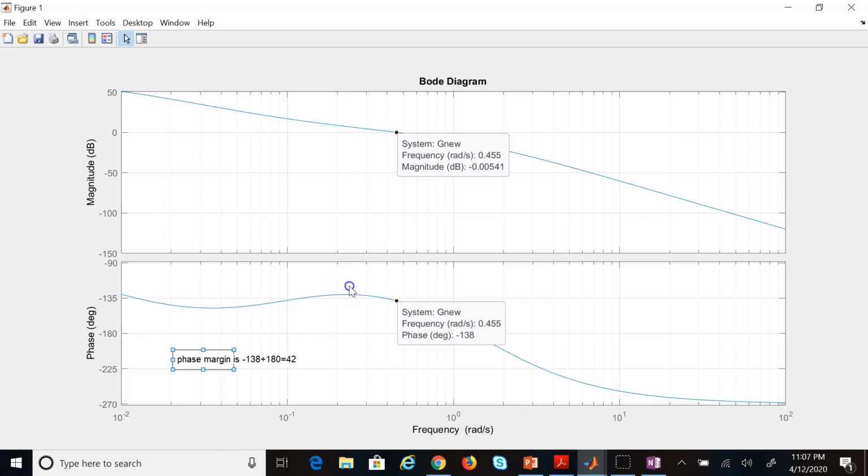So you see, I added 12 extra degrees to the required phase margin of 40. So I was shooting for 52 degrees phase margin, but what I got is 42, right? Because this lag compensator shifts the gain crossover frequency. But still, this is more than 40 that I wanted, so I'm good.